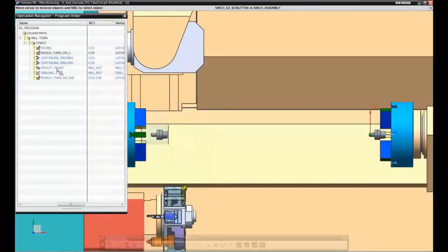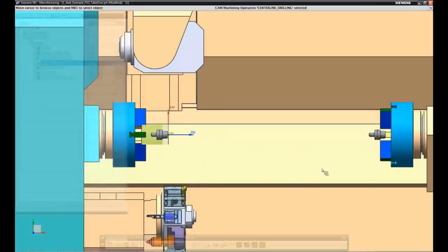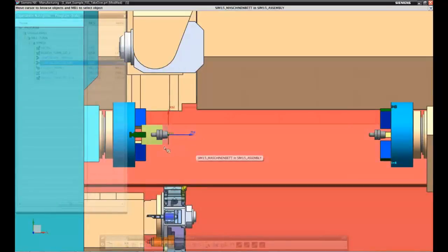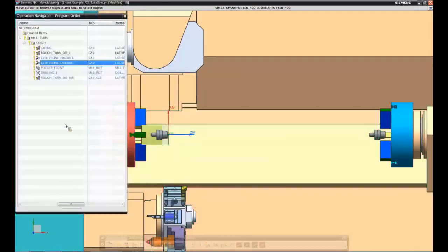There is a cycle in the numeric controller which moves the sub spindle to the main spindle, and it moves the sub spindle until it hits the IPW, until one of the clampings is hitting the part here. And you type in a certain pressure where the machine is moving, and until it hits the part, it stops moving, it grabs the part, and it moves back. And this, as I say, is a special machine tool cycle which I can simulate in NX.